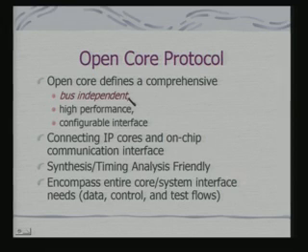And why it is bus independent? Because you will be actually defining the bus which is consistent with the protocol, because a protocol can have a variety of transactions defined depending on your requirements and the device characteristics. You may define the bus. But if I pick up an IP core and if I say that my IP core is compatible to that open core protocol, that means it can support the transactions which are being defined as part of this protocol.